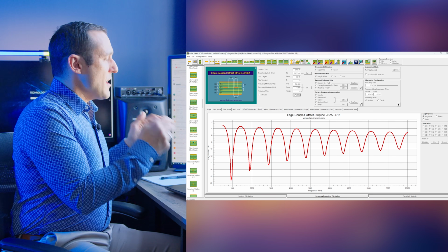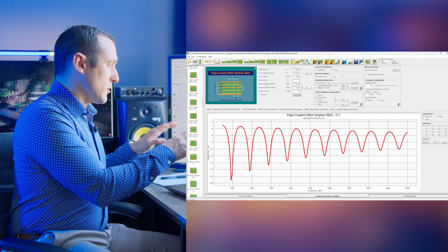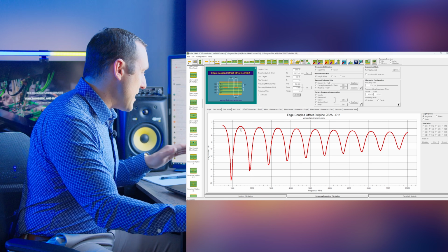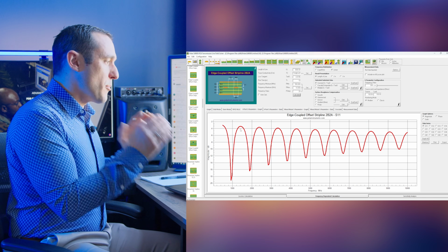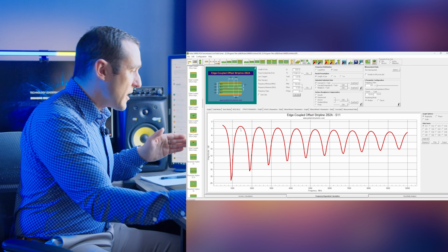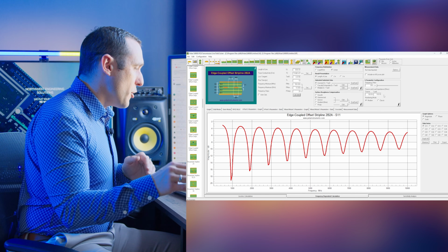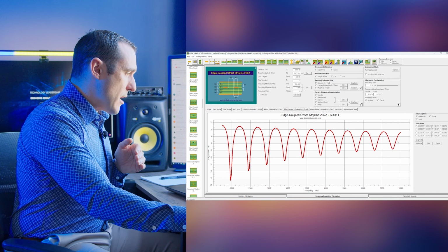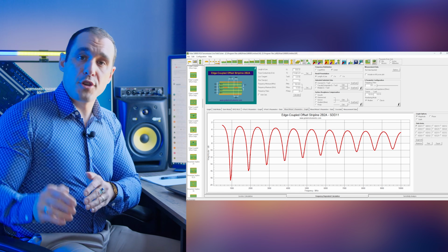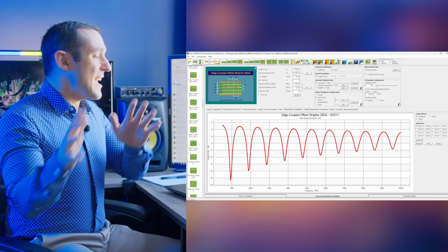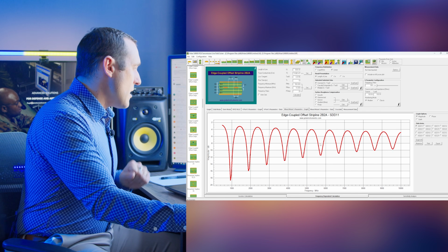Now you can see here on this graph with the S parameter results that this return loss for this particular line is pretty unacceptably high. The peak goes all the way up above -4 dB. So that immediately tells us that this proposed design is not going to work in an interconnect that is terminated to a target impedance of 100 ohms at the source and the load. We can also look at the mixed mode S parameters, which is of course very useful because it lets you separate out common mode signal from differential signal. And that's something else that I've discussed in another video about length tuning. And you can get all of that data right here inside of SI9000.